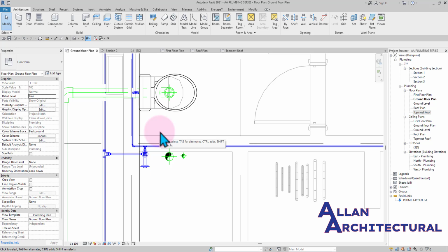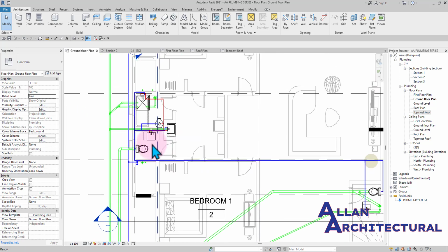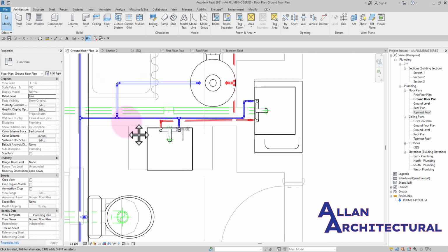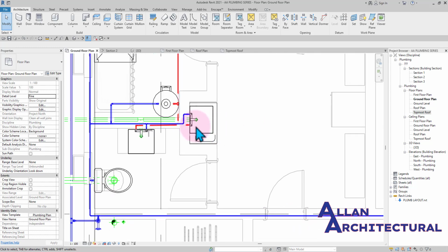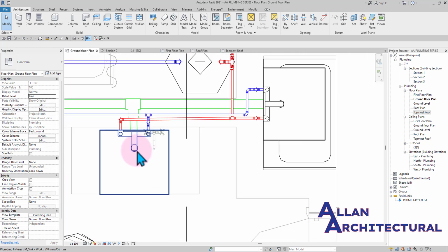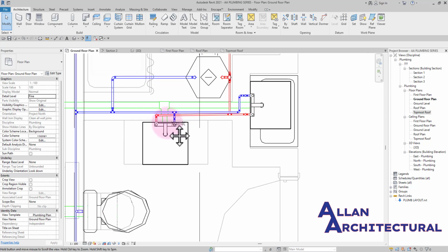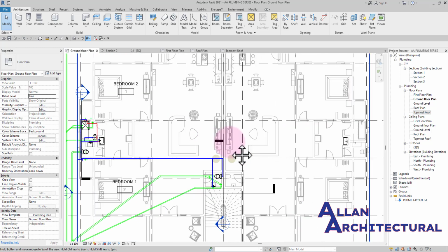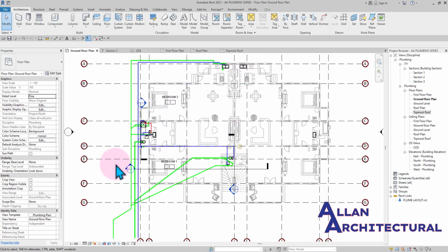Sometimes you want valves in all of the spaces. Like I said, most of the times in the kitchen, we usually put in angle valves to be able to control all of the stuff inside of the kitchen. So the angle valves, we can even use it to control the pressure of the cold water supply. If maybe the water is coming in very fast, we can use the angle valves right under the sinks to kind of gauge it and control all the stuff in there, which is perfect. All right, so I'm going to skip all of this and get into serious business on how we can actually create some stuff and check some stuff.